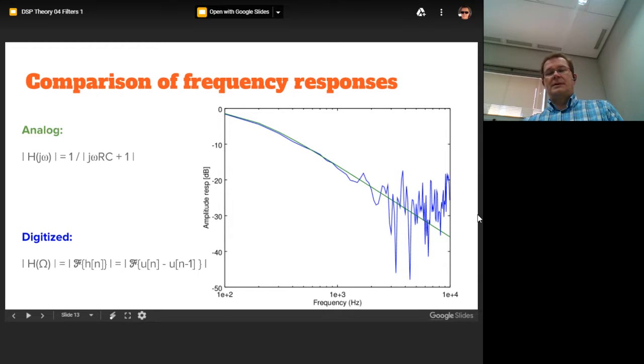For example, one is the noise on your data. You have always noise on the data, so I have only about 25 dB signal to noise ratio. That's not even close to enough to actually get a good measurement of this impulse response.